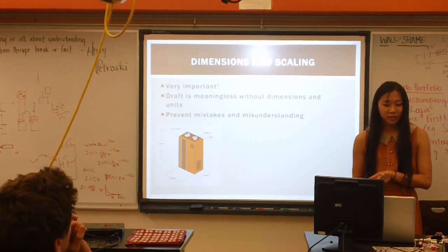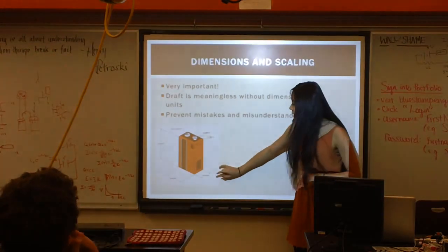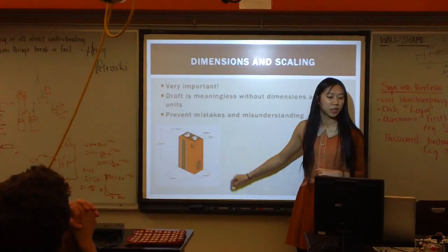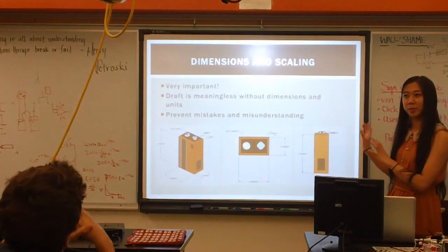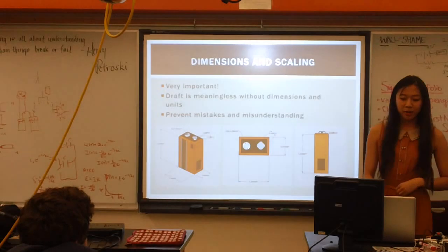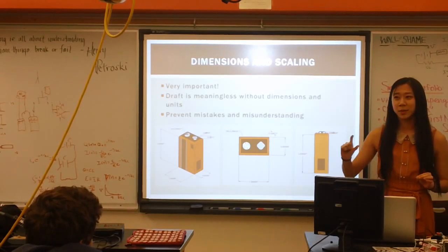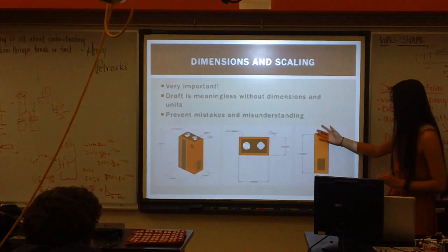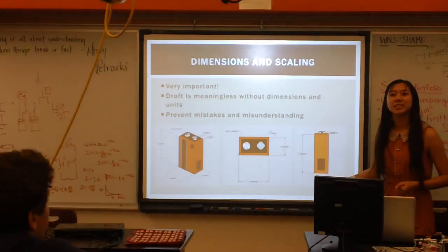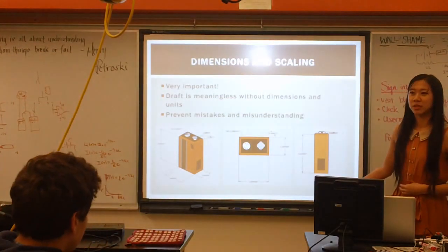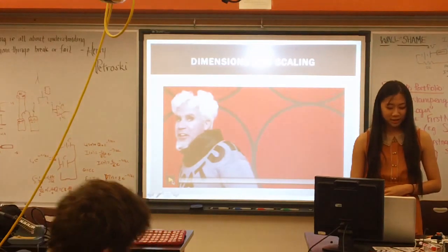And so a lot of times formally we'll have a dimension picture portrayed in isometric view like this, where you've labeled all the sides, all the different parts. And other times, sometimes we'll use the same orthographic projections and just have the dimensions as shown here. The important thing is just to make sure that your dimensions are fully defined, and so you have every aspect of your object actually labeled. For example, in this orthographic view, if I had forgotten to label this side, nobody would know how big to actually make that. And then this is just an example of why dimensioning is important.